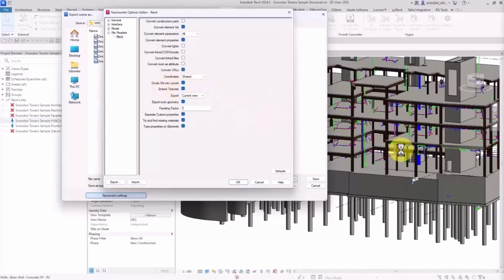But here, this item is modeled from the base till the top. And when we select this item, we don't cut it. It can be useful for facilities. As an instance, we have two levels and we have some facilities under the roof of the lower level. And the facilities are minus 4,000 millimeters under the roof. And this can be confusing in Navisworks. In this situation, this option can help us. It will analyze and select the reference level automatically.